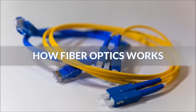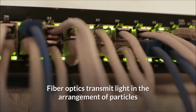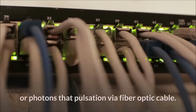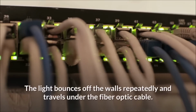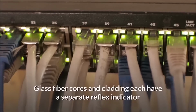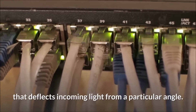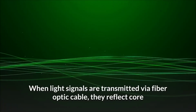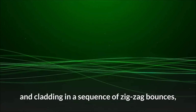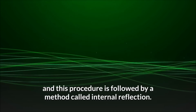How fiber optics works. Fiber optics transmit light in the form of particles or photons that pulse via fiber optic cable. The light bounces off the walls repeatedly and travels down the fiber optic cable. Glass fiber cores and cladding each have a separate refractive index that deflects incoming light at a particular angle. When light signals are transmitted via fiber optic cable, they reflect off core and cladding in a sequence of zigzag bounces, and this process is called total internal reflection.